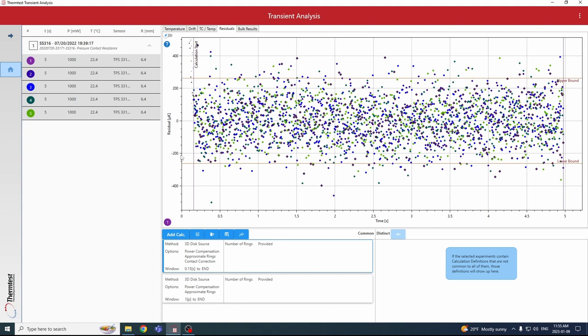If you had any behavior at the front of the residual, that could represent nonlinearity, that could represent the contact resistance. The back end of the residual pattern, if you see any behavior there, that could represent effects of reflection. The second way is if you want to manually remove those points and iteratively approach removing the contact resistance.